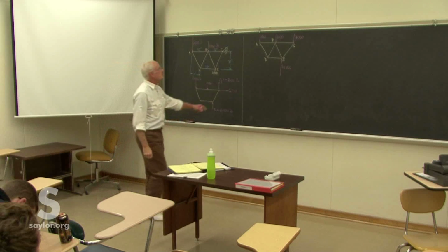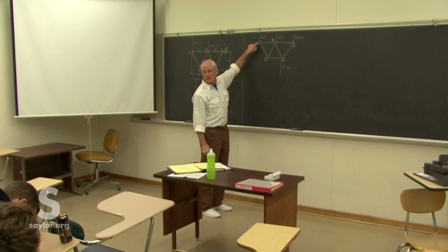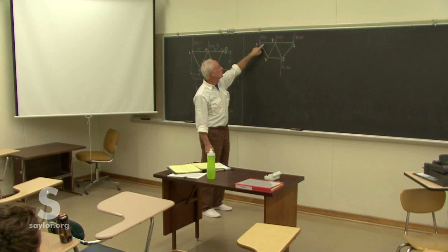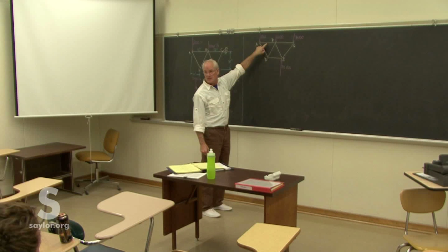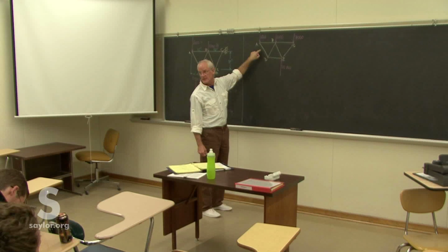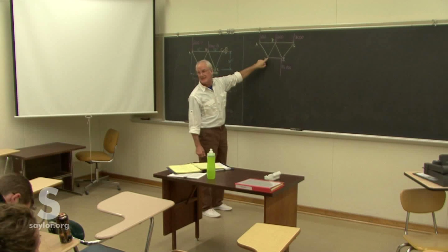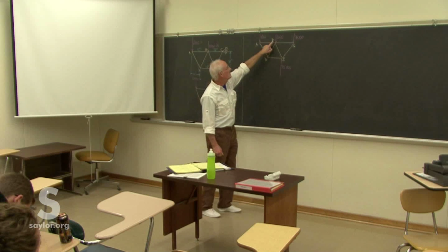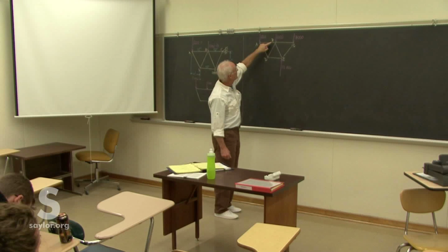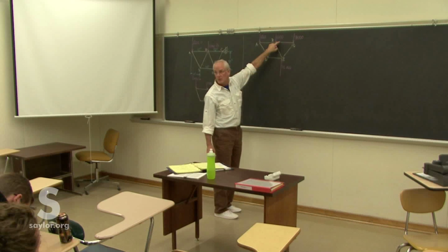So notice that at joint A, we have two unknowns. We don't know how much force is coming from that member. We don't know how much from this member. And we have one known. Joint D, three unknowns, no knowns. So we certainly don't want to start there. B, one known, 1, 2, 3, 4 unknowns.